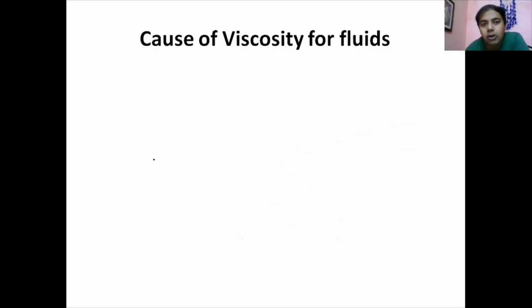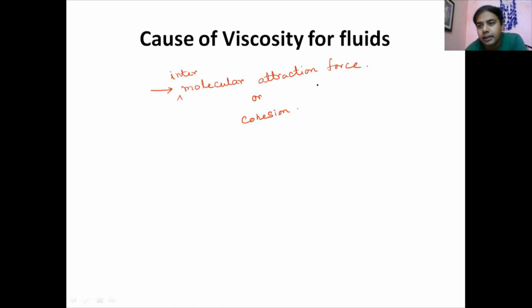Now the most important thing, what is the cause of the viscosity? Basically, there are 2 main causes for the viscosity. One is the intermolecular attraction force, the attraction force between 2 molecules, which is known as the cohesion. Another reason is the molecular momentum transfer.